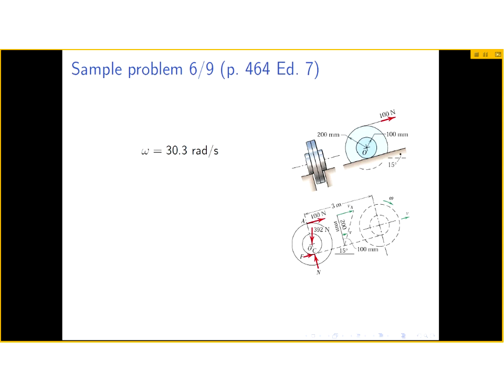Now, the second question, to answer that, I've just calculated the result on this slide. The second question asked, what is the power at the instant when the masses move 300 meters of this 100 Newton force? Now, to calculate the power, we've seen that it is simply the dot product between the force vector and the velocity vector. In this case, clearly the force vector and the velocity vector are 100% aligned. The angle between the two is 0. So this product of two vectors is quite simple in this case. It's simply the magnitude of 100 newtons times the velocity of the cable.